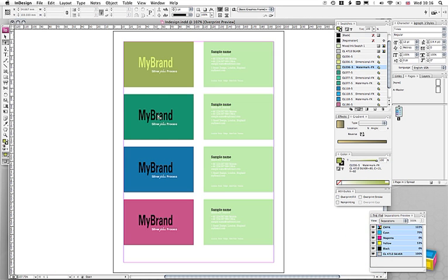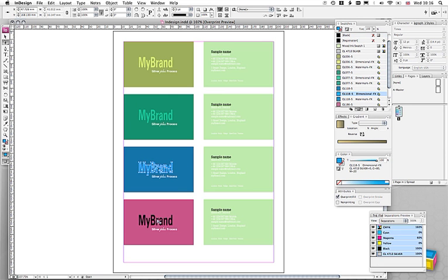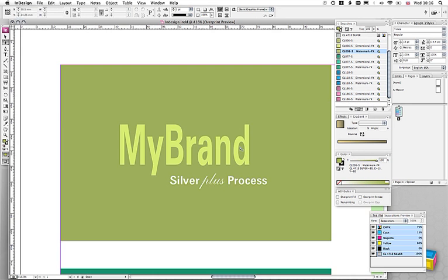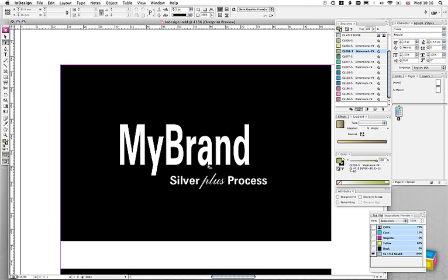We'll zoom out and we'll apply this to all the other ones, so we're going to have a dimensional effect for each of the areas where it says My brand, and make sure that the dimensional effect is always the same colour as the background but without the metallic. Turn off the CMYK, you'll see that we have no silver in this area. Dimensional effect is controlled by having non-metallic areas next to metallic.